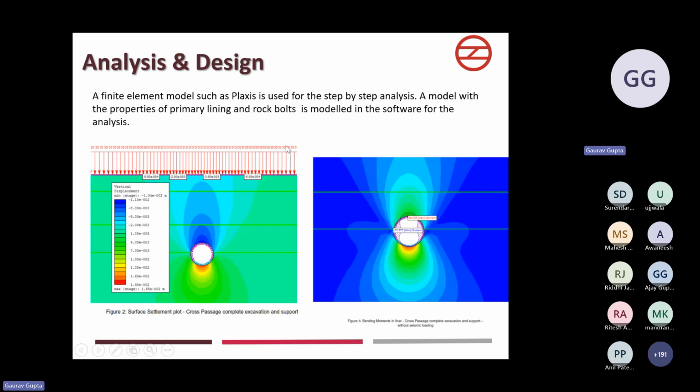So a similar FEM model in Plaxis has to be prepared. Like this, I have shown a typical cross section of a cross passage in which the soil has been modeled, surcharge has been applied, and then stage-wise we will show the construction sequence. Similar to the sequence we have prepared, the same we will input in the software to get the desired bending moments and shear force for the design.